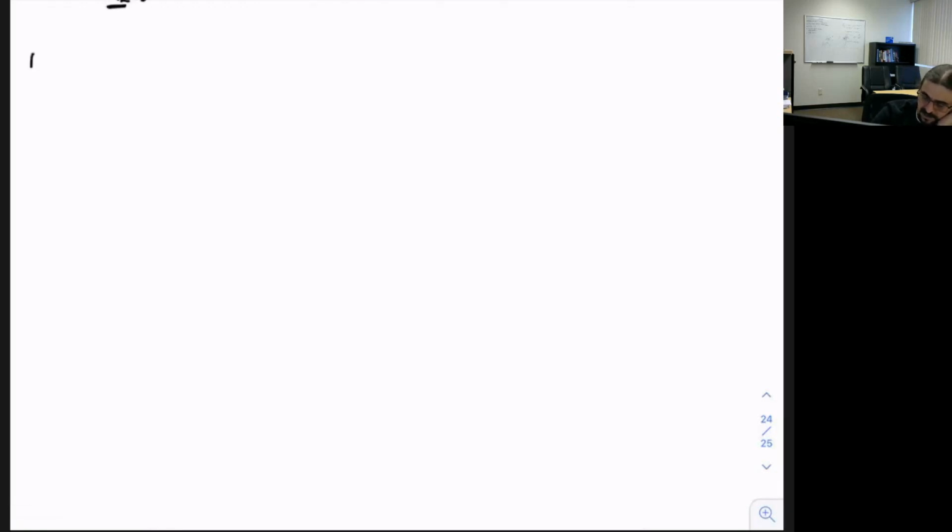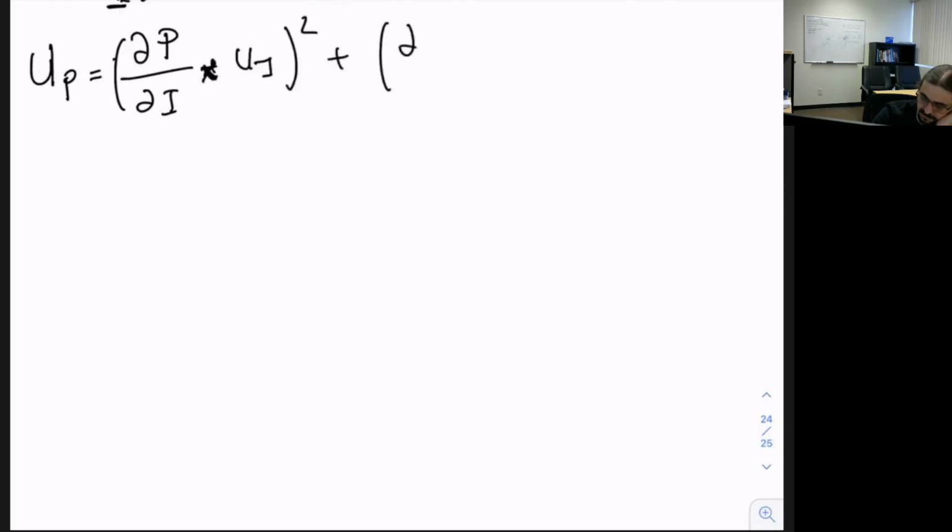Remember that the uncertainty of power was defined as dP/dI times UI squared plus dP/dR times UR squared, and all of that goes into a square root.